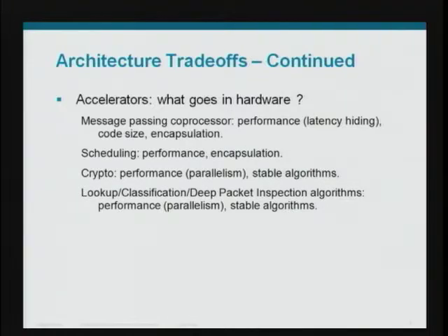So if we're going to put in, let's say, a regular expression engine, how many processor cores are we trading off? And then what type of feature mixes and how important to our end customer is having the regular expression versus those additional 2 processor cores? And that's the kind of trade-offs we did. We came to some conclusions that 2 areas we did want to significantly offload from software were crypto and scheduling. So just hit those a little bit more.